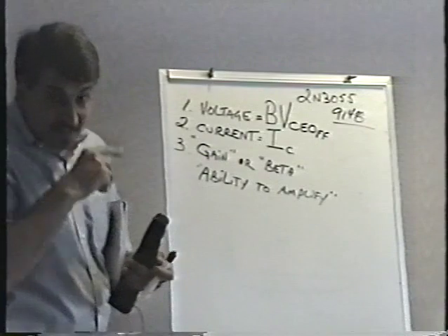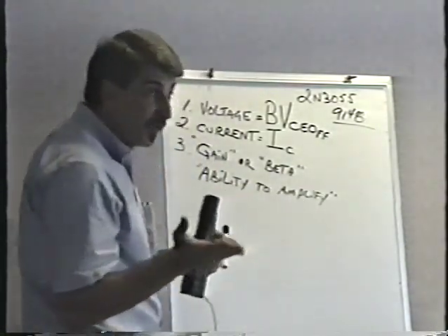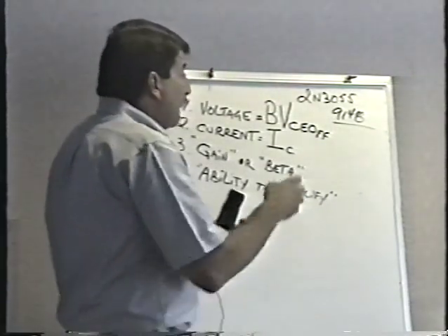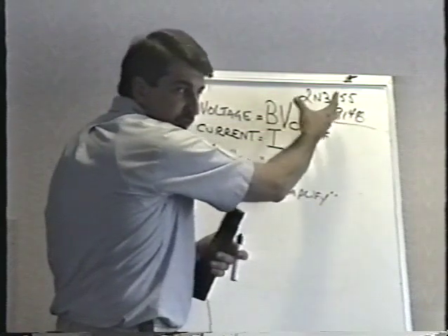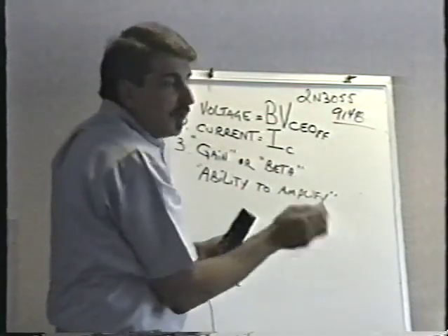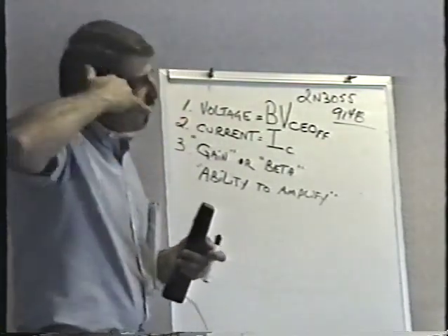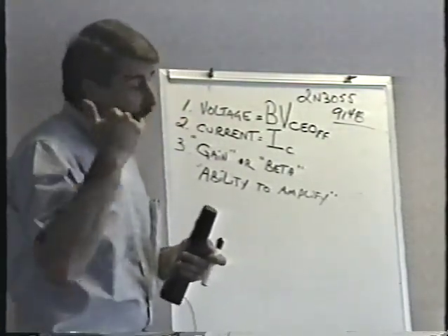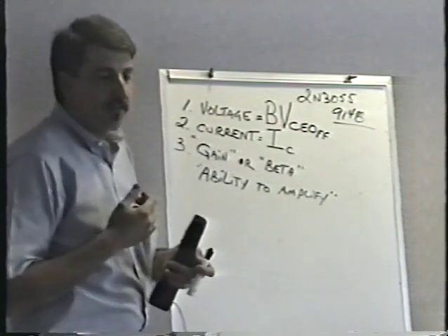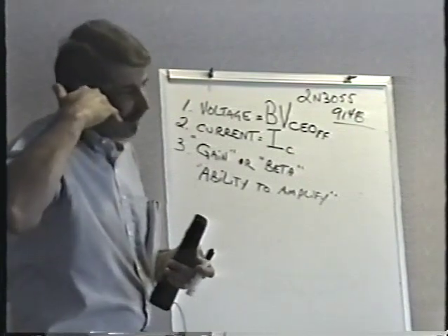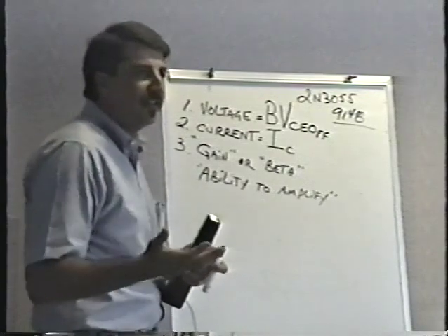Be careful about this. Almost every part has a date code on it, in addition to the part number. So if you see a number where the last 2 digits are 52 or less, and the first 2 digits look like a year, you're not looking at the part number. Every now and then I get a call from somebody: Randy, I'm trying to find this transistor. What's the part number? It's a 9016. Oh, no such transistor. Yeah, man, I'm looking at it right here. No, that's a date code.